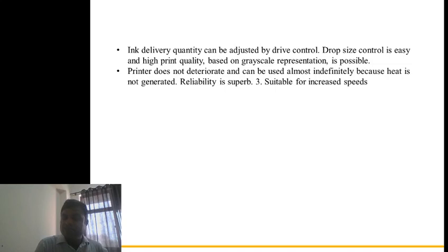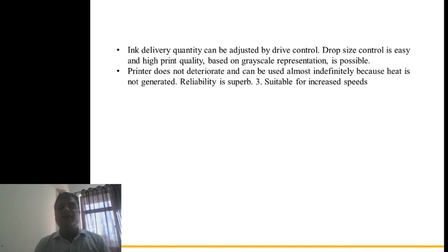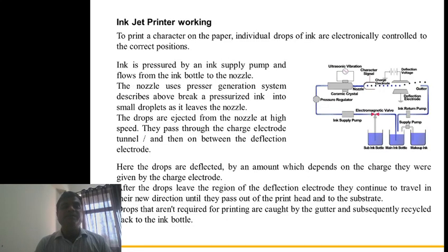But in the previous case we are creating heat, and due to the heat the system will deteriorate with time. So if you consider reliability and print quality, the piezoelectric pressure generation method is more reliable and provides high quality print output in comparison to the thermal generation method. The speed of printing of this technique is also high.